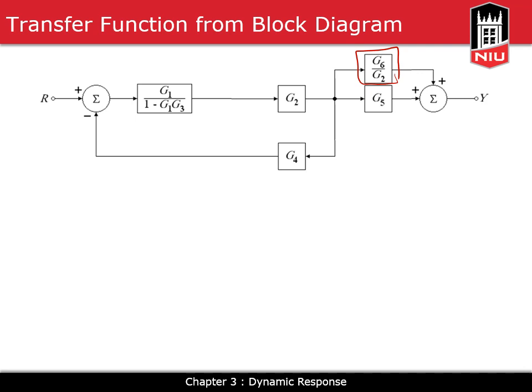Now there are multiple things we can do. Let me first clear that. First, you can see that these are in parallel. The two blocks have the same input. Their outputs are getting added up. So we can just add up the two transfer functions of the two blocks.